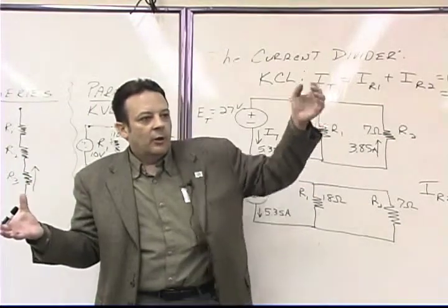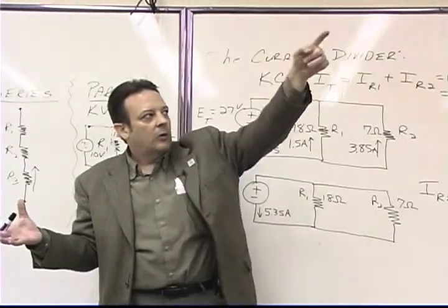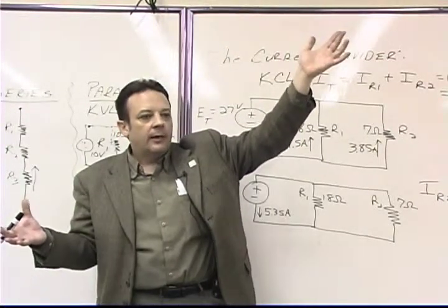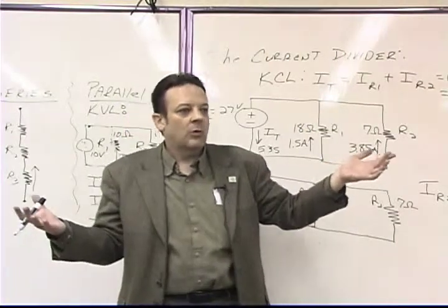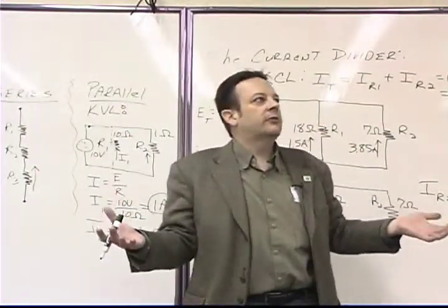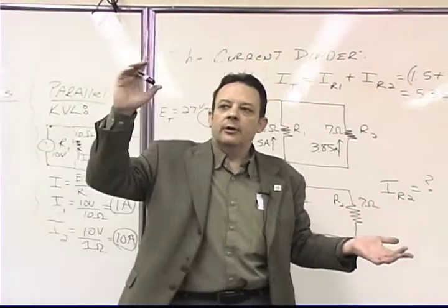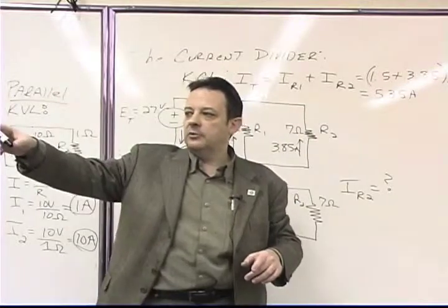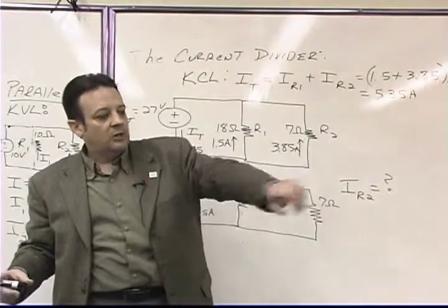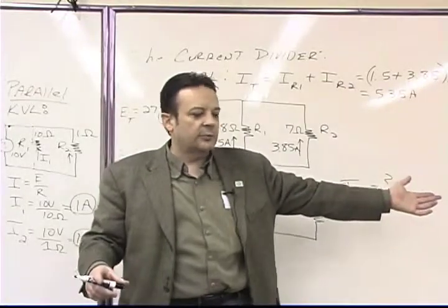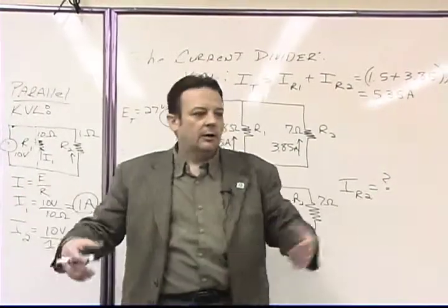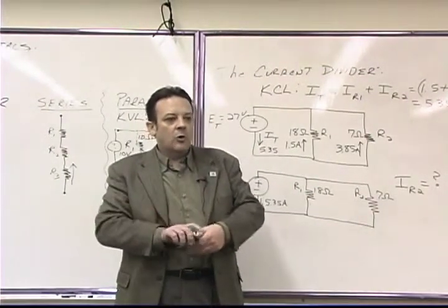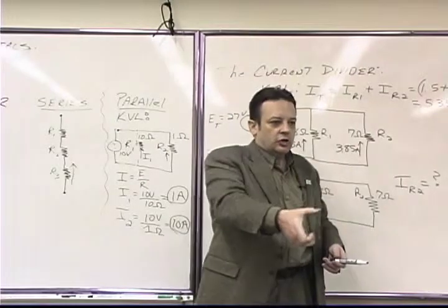Okay? And so they'll run the wire back there, and they'll run the wire over and through the rafters or up in the attic area, and you won't be able to see it. You walk around, you do a visual inspection, and it's like, okay, where are all the loads? Oh, well, there's a lathe over there, and there's a server bank over there, and there's a CNC milling machine over there, and there's 15 motors over here running this process, and there's a big pump over here, and that's all. And so then you'll get a table, and you'll fill them all out, and you'll go around with the clamp on meters, and you'll check all the currents.